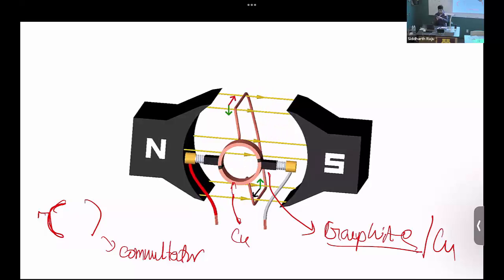If you look at these copper rings when I pass them around, you can see there's a layer of graphite residue. When this becomes thick enough, it can connect two different copper rings together, effectively shorting the rotor windings. So there are a whole bunch of problems that occur with graphite brushes. You can instead use copper. But the problem is when you have two metals, copper against copper, rubbing past each other can cause a lot of scratches on the commutator. The copper brush might not wear out, but the commutator itself will start to wear out. You'll have pitting on these, which can then start to arc. You'll see a lot of arcing and so on and so forth.